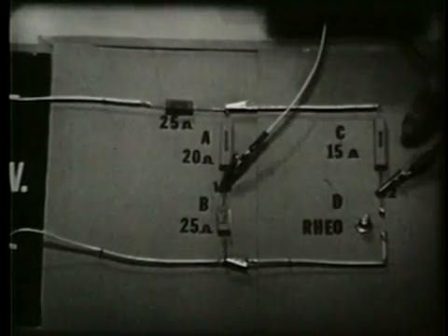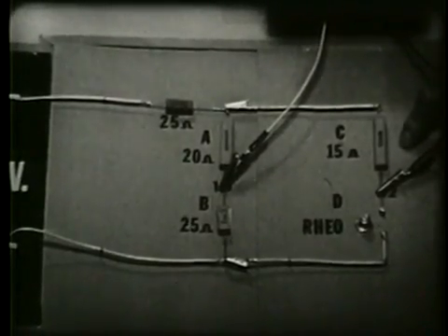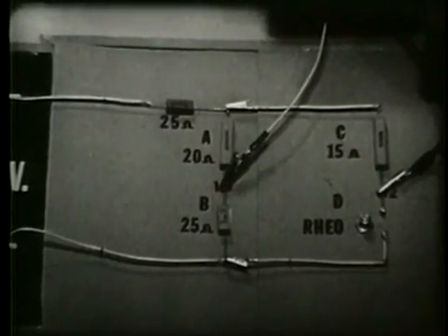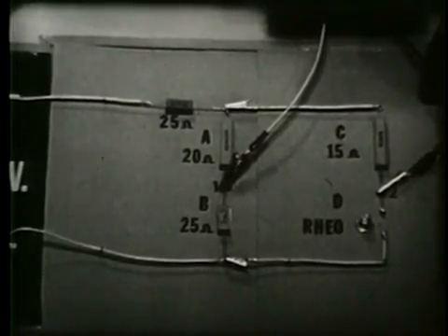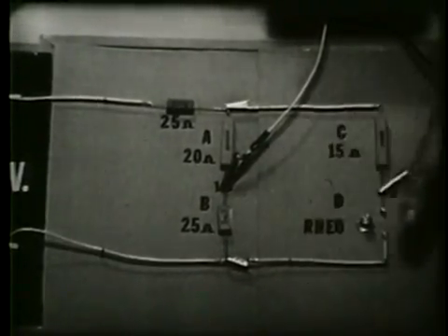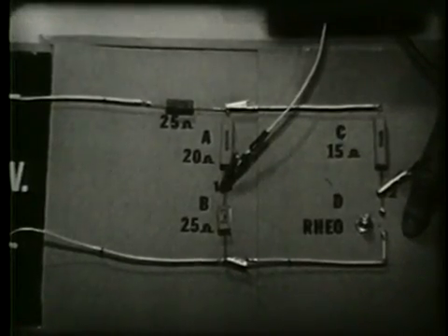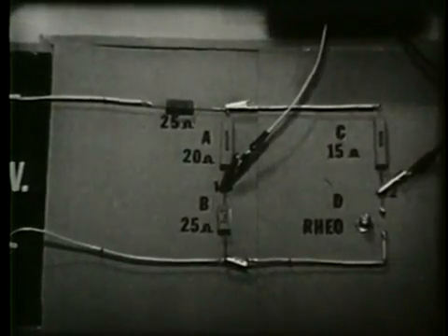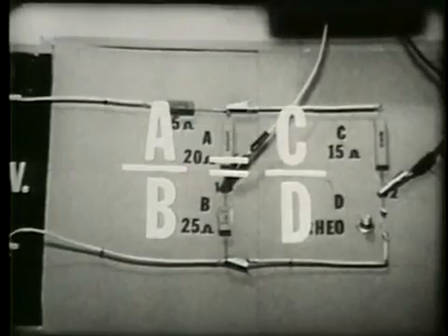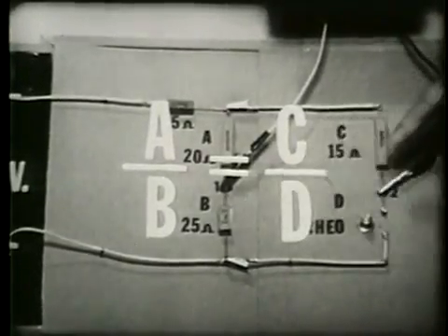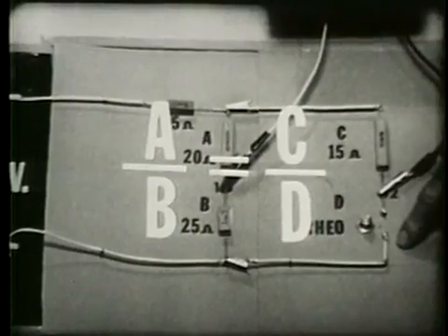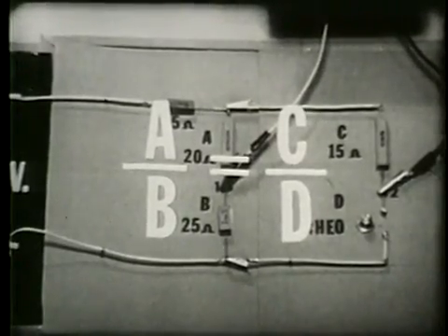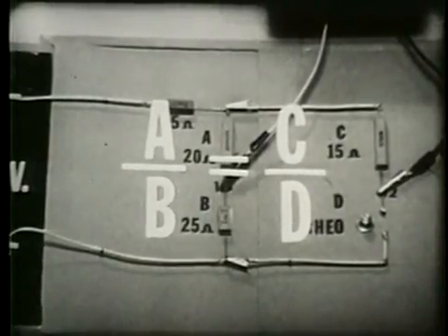Voltage A is exactly the same as voltage C. We proved that in 2 ways. We measured the voltages, and we have no current through the meter. This action also proves that voltage B is exactly the same as voltage D. This means that we have an exact ratio between voltages A, B, C, and D. This ratio is A over B equals C over D. It is not necessary that we know these voltages. If there is 0 current through the detector, this ratio is always true.